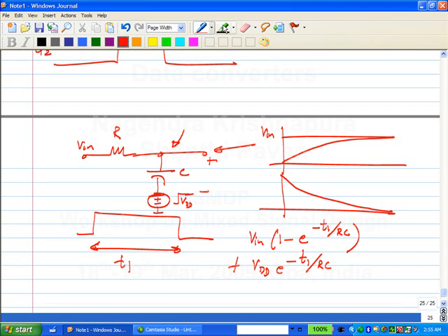Does that make sense? So if it doesn't forget the old input adequately, what do you think will happen? Let's say RC is not low enough. What do you think will happen? You have made an error because you are ideally interested in sampling Vn.